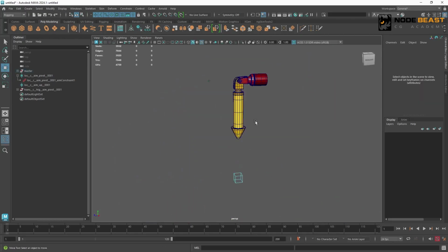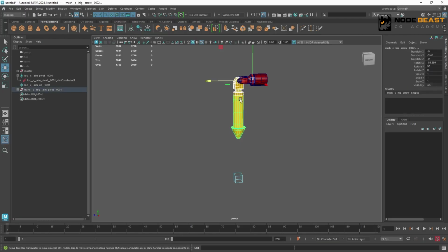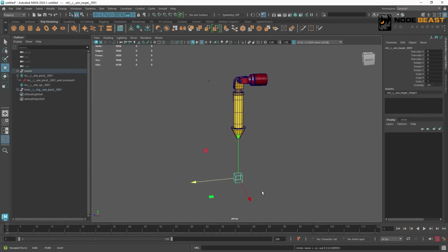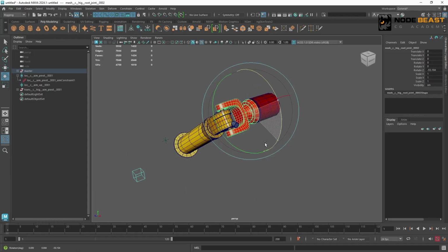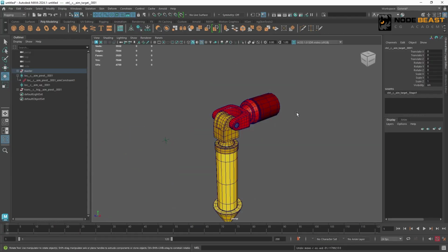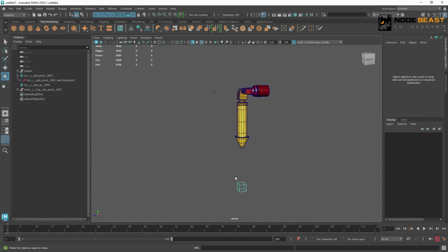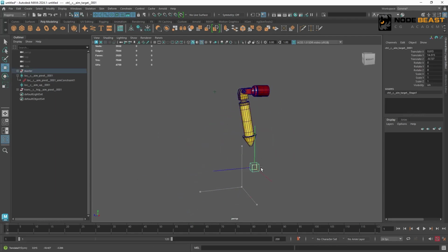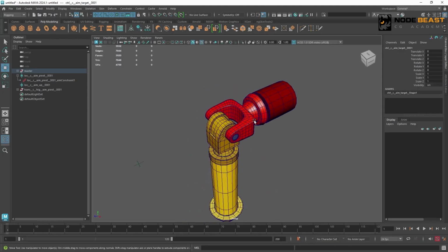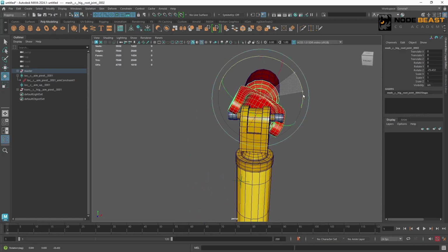So here, let's think about how to achieve this behavior. First thing we need to do is separate our rotation axis. We know this object, our small arrow model, rotates back and forth. It actually also rotates left and right. It's just that when it rotates left and right, we need our base model to rotate along with it to keep the connection between them consistent. So our arrow model itself is moving normally in X, Y, and Z. But what we need is for our base model to follow along on the Z-axis rotation.